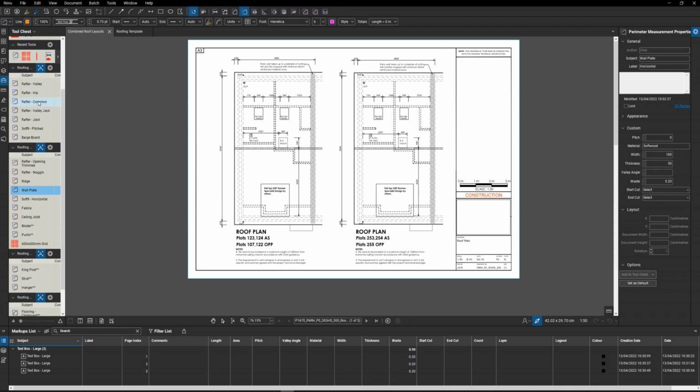And what you can also do with all of these is, you'll see here, waste. So I'm adding on an allowance to each length of timber for a waste on the cuts. Now on this one I've done 200 mil or 8 inches on the wall plate, so that allows for some laps and some joints. Ridge waste is 200 mil. I mean, these are fairly short lengths. If I was getting into scarf joints and things like that, I might add more onto it. Noggins, well, I've only put 4 inches, 100 mil.